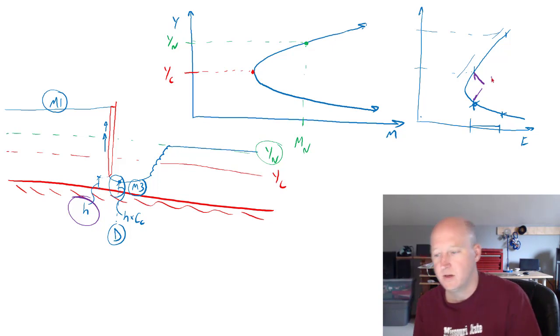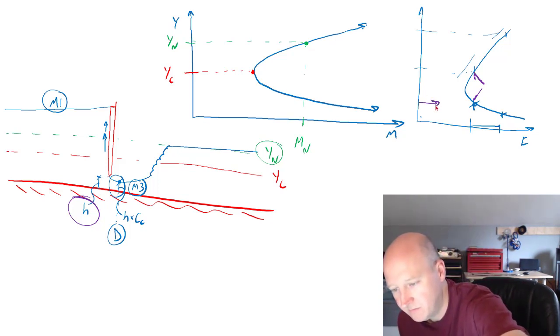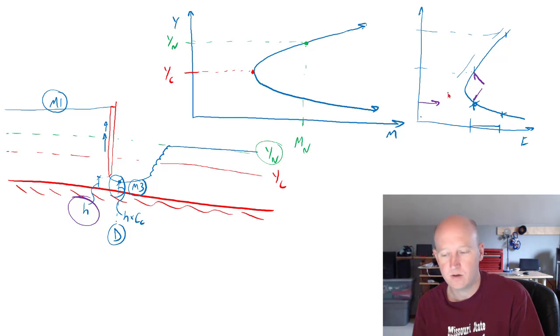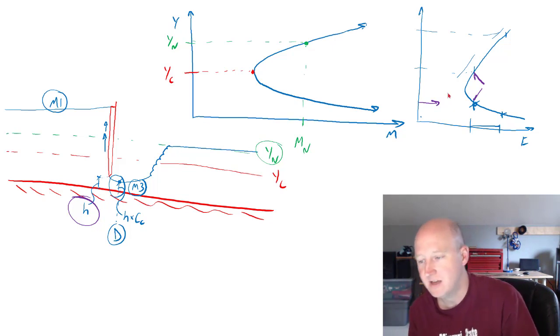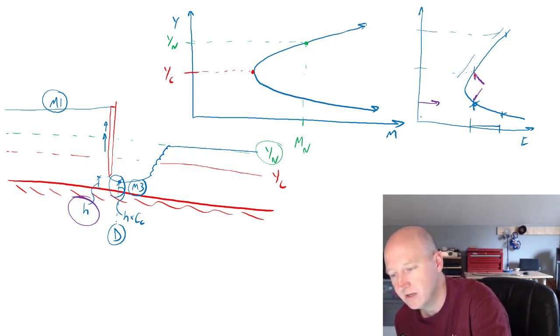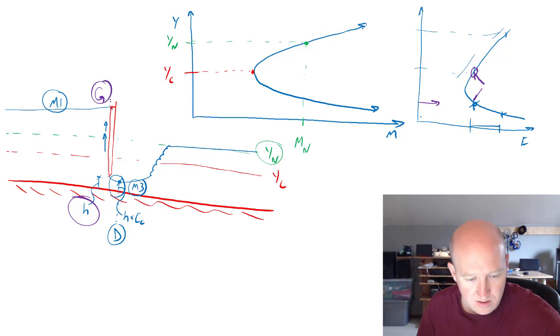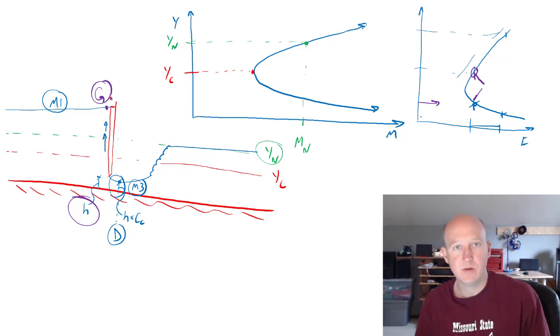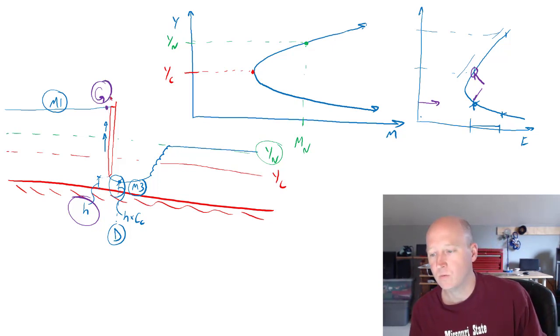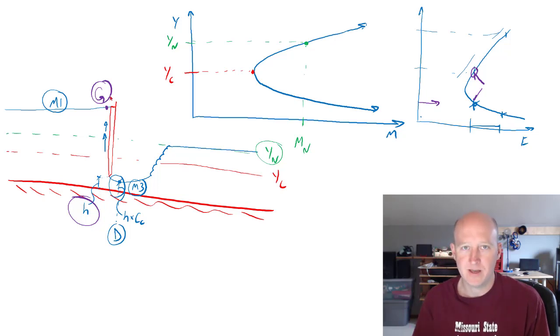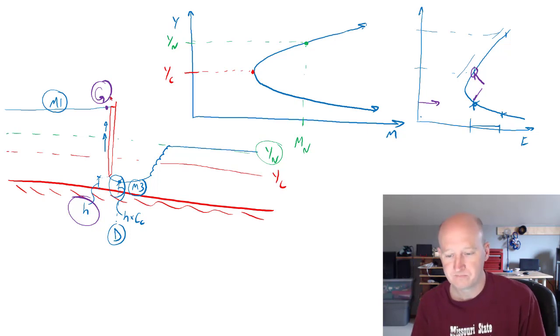And so if this point is fixed, given the depth at D or the height of the gate, then it's directly related to what's going on upstream. And so the energies at section D and at section G are going to be the same. And so you can see how as we lower the gate down, you need more energy to pass the water flow, and that means that the depth upstream of the gate needs to go up. So this is pretty intuitive.